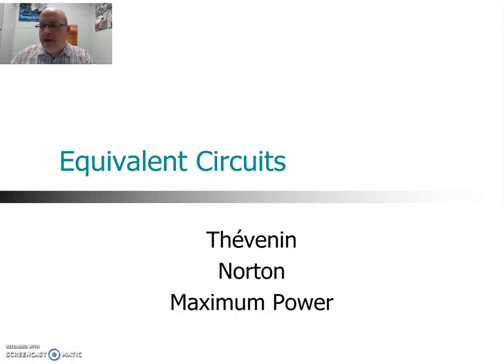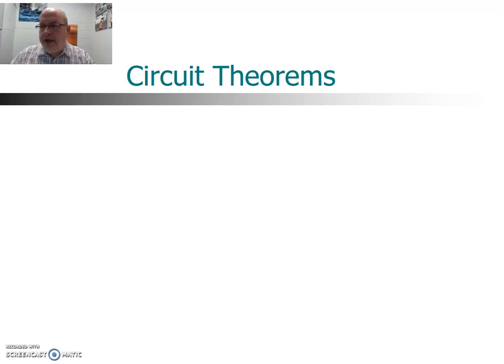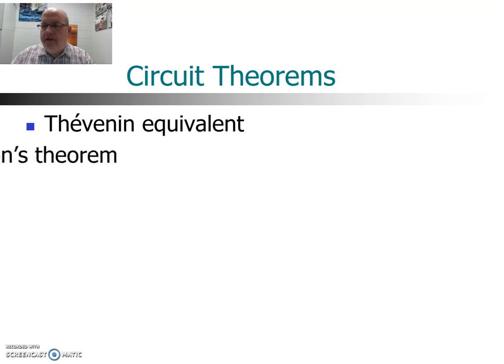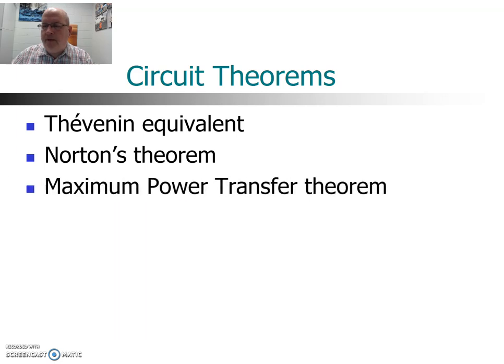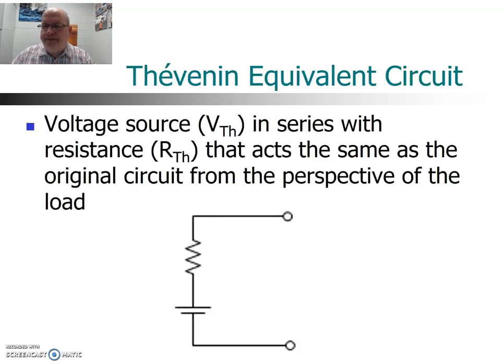This video is going to look at circuit theorems, which tells us that we can build an equivalent circuit that will take the place of an original and be much simpler. First of all, we're going to start out with the Thevenin equivalent circuit, and then we'll examine briefly Norton's theorem, which talks about the Norton equivalent circuit, and maximum power transfer theorem, and these are all related to Thevenin.